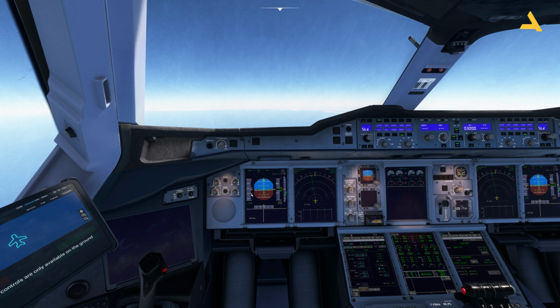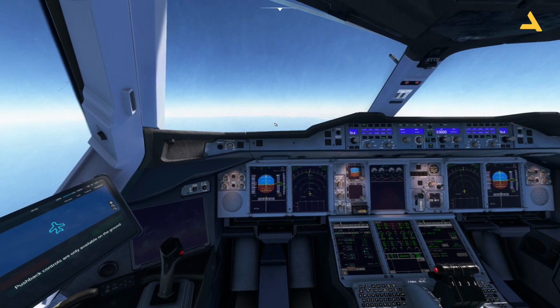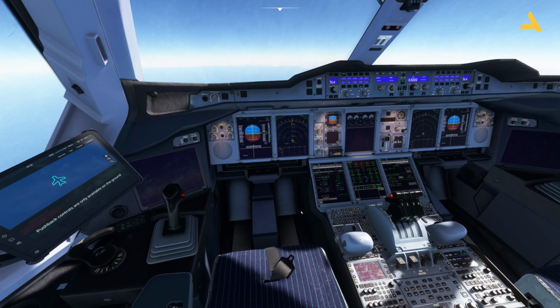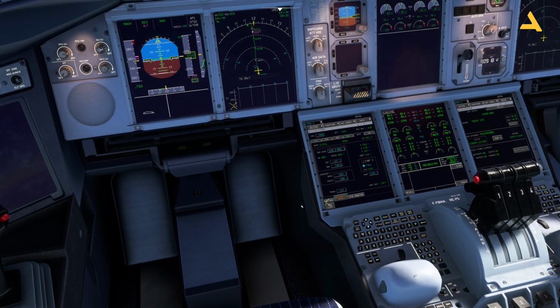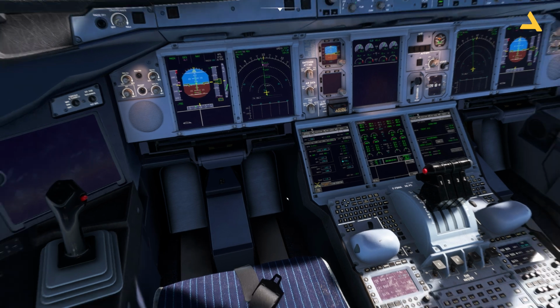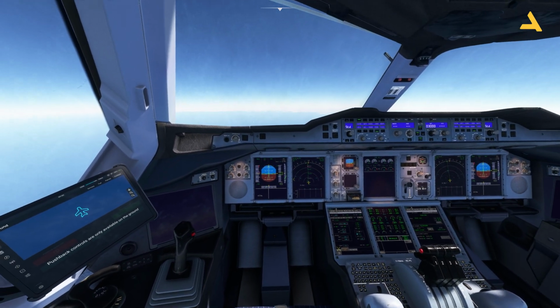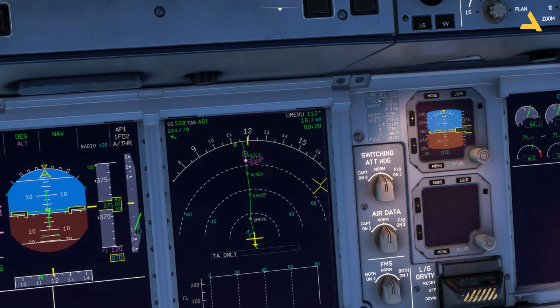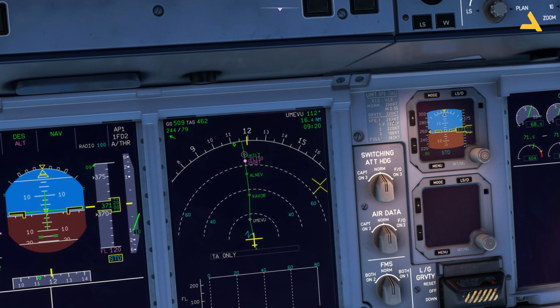This is the green dot speed, and this indicator shows that by this point the plane will be following the descent profile. Right now it's slightly low as I've started it early. Now just before the runway, not so short of the runway, but during the arrival I will also activate approach, reduce the speed, and then extend the flaps. You can see these speeds are coming at which you can have flaps. So below 182 knots you can have full flaps.